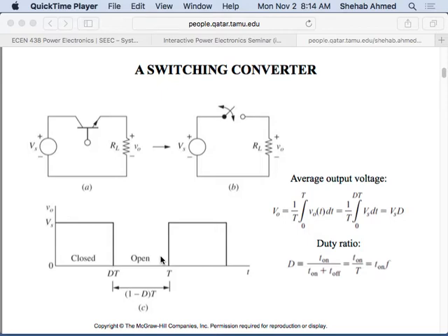So for waveforms that have quite a bit of harmonic content, like pulsed waveforms have, they contain almost an infinite amount of harmonic content, right? If you have a pulse, you have many frequency harmonics contained in that pulse. So in these cases, if the motor is very far away, then you would require a filter. If the motor is very close to the inverter, there is still no need for a filter because the motor itself, the windings act like the filtering elements.